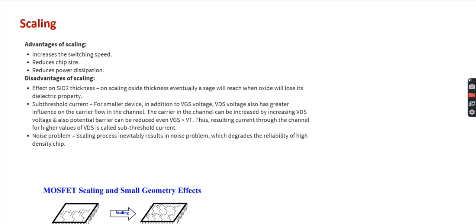When does glitching power dissipation occur? Earlier we might have assumed that all the gates have zero delay, but in reality, gates have some finite delay. Why? Because as you studied in CMOS, you design the circuit with the help of the layout diagram, using materials like metal 1, metal 2, polysilicon, and N-well. So many CMOS layers will be there, right?